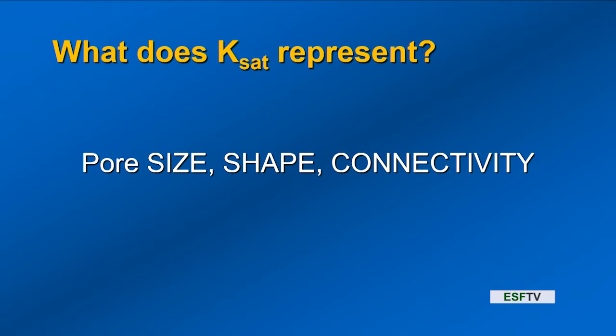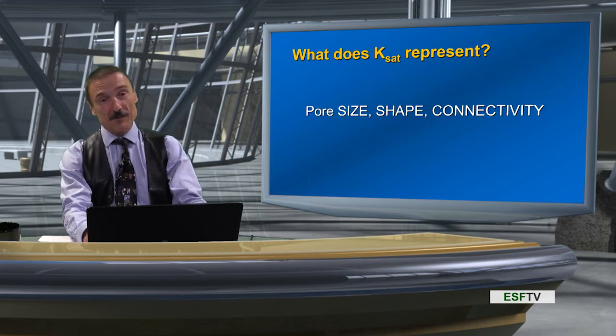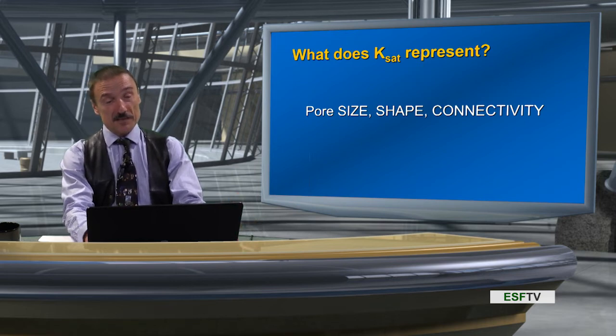You can go through any of the soils of the US and the NRCS, and they post numbers that express Ksat for almost any soil series. And that's one of the ways we model soils and movement as we think about using the information from the soil survey, to have an idea of the rate of saturated conductivity. That has all kinds of uses, right? When you're thinking about drainage, when you're thinking about septic tanks. So that Ksat is a very important number that expresses the integrated movement of water. It's very important in soil physics and very important in practical applications.